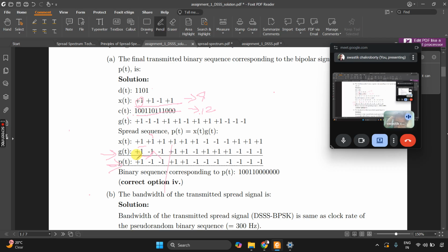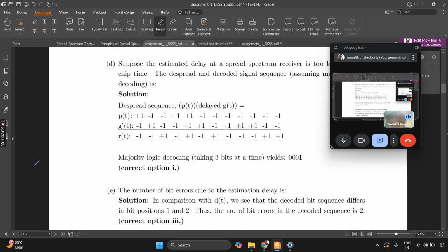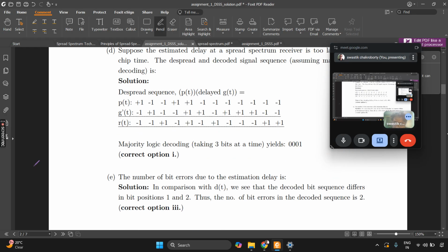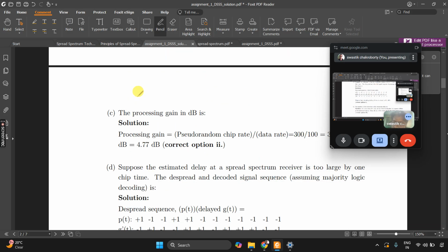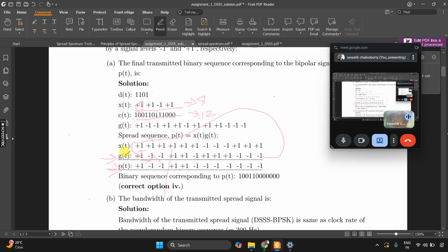Finally, in the vacant space left in the first spot, of course, because the PN sequence is a feedback shift register, a cyclical process, we will get back the minus 1, which is rerouted here. So we have the delayed sequence, and our spread sequence is, of course, sitting at the transmitter.